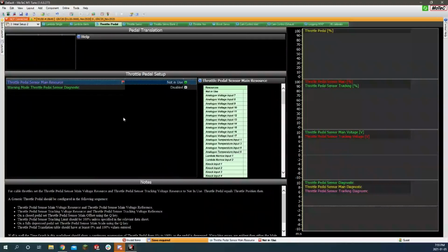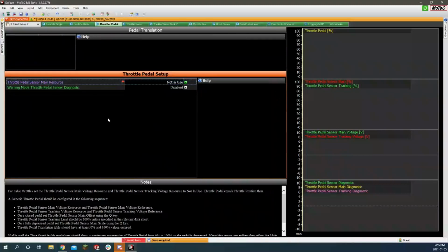It's all stuff about how the ECU knows how much throttle you want and what to do if the throttle starts going wonky. If you have a bad signal, if there's interference or a bad connection, the throttle will start behaving not like it's supposed to, and the sensors on your pedal and on your throttle body, if they don't match, it goes into error mode and it closes the throttle, stuff like that.